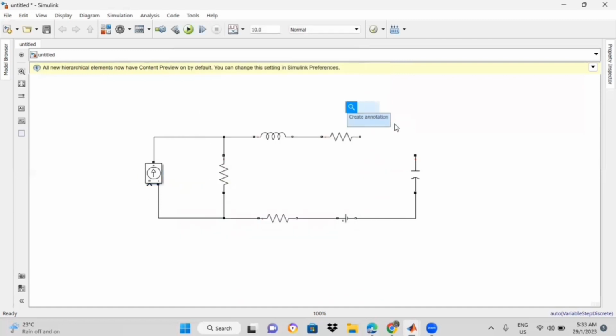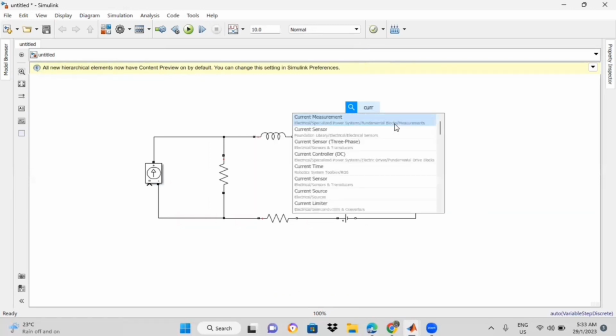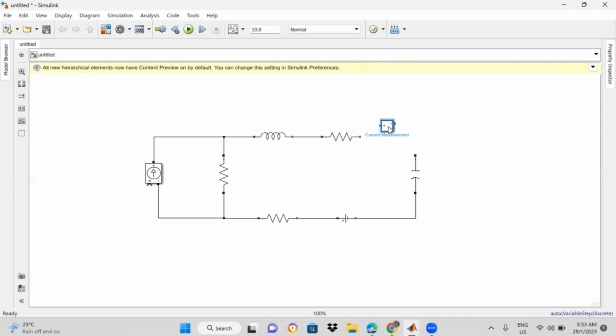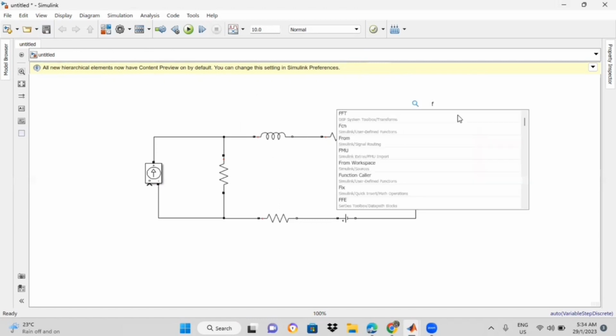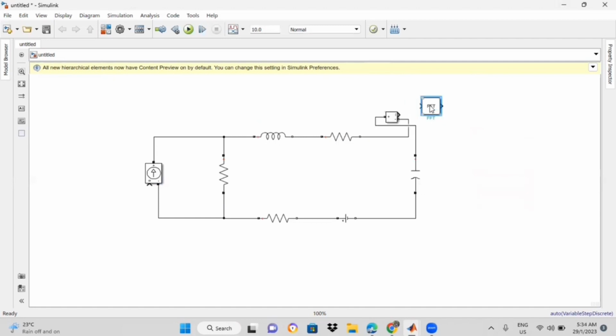After that, we connect an ammeter into the node or the branch that we want to measure. And then we connect the polarity of the ammeter, and this is quite crucial, and we need to focus not to make any mistake in connecting the polarity.